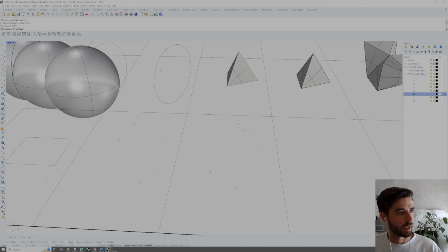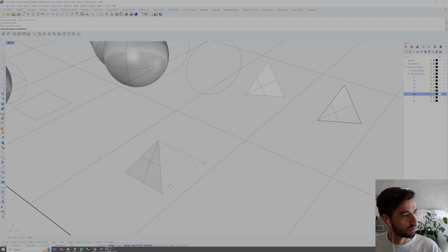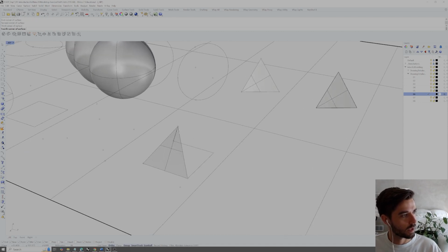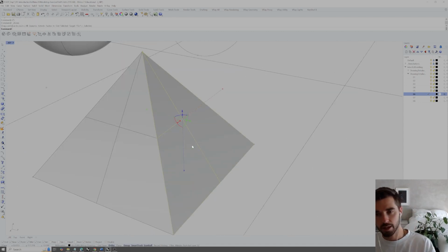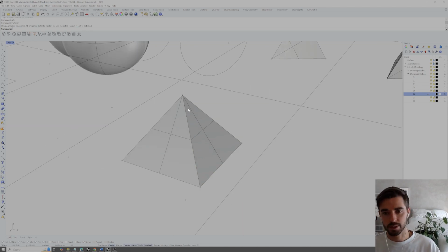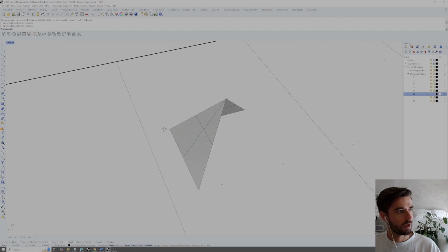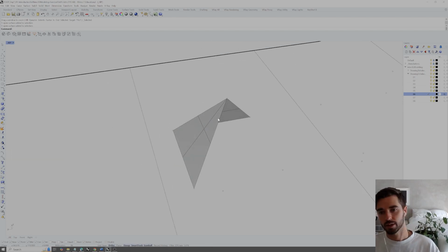So we can just go ahead and do it clockwise, counterclockwise, from this top point to this bottom one, so 0.2, 0.3, and then back. Then we can just go ahead and do these all the way around like we did for the last one. And again, I'm drawing out 4 points here, so back to the original one, just to control our surface trimming so that they are non-trimmed surfaces.